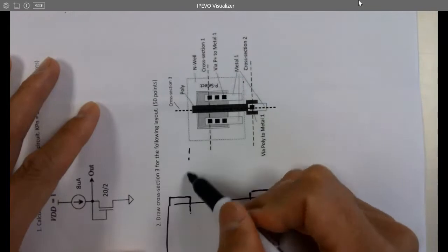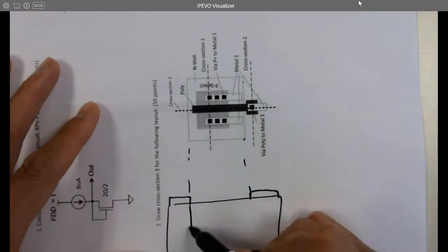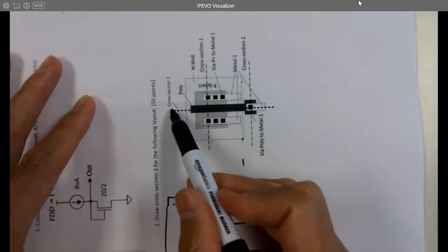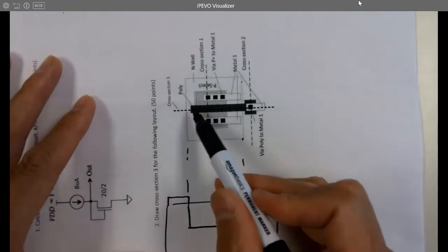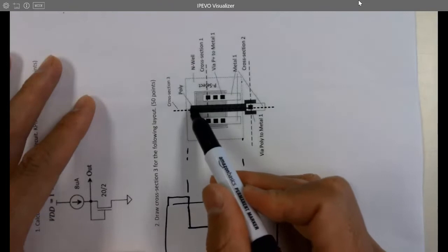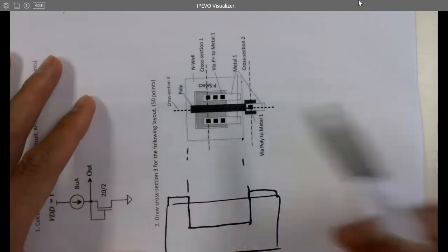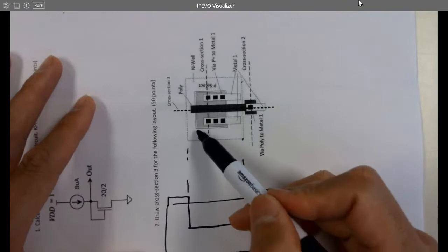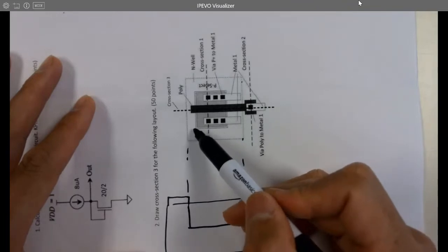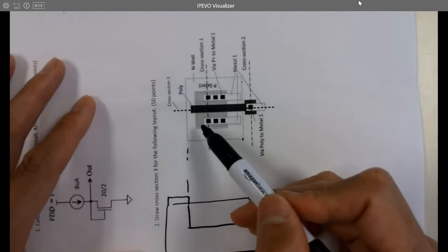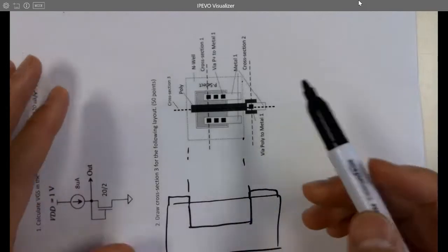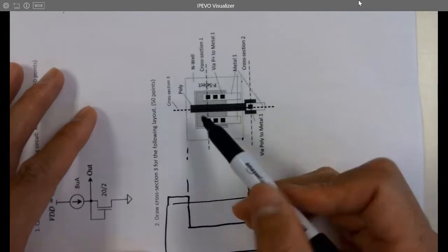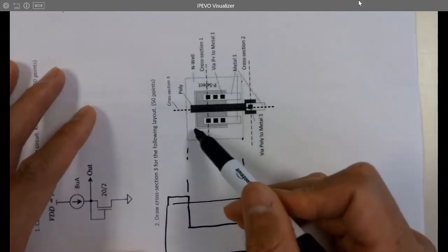So here's going to be the N-well. The line is drawn here. And that's a gate, right? So the gate is on the top of P plus. And here's a P select and P active. So which one defines the area of the P plus? P active. The inner one, the outer one. Yeah.